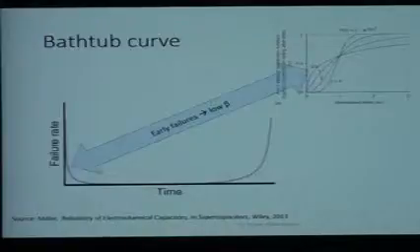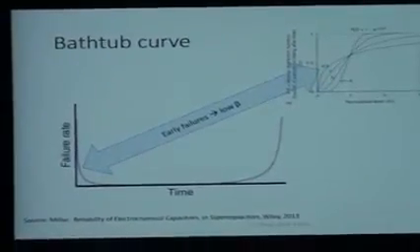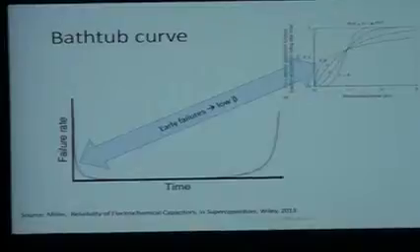Okay? So in order to handle this, I'm showing you in the inset here, if you have very low shape factors, beta, right? If you have very low beta, then that can handle the early failures. It has sort of an effect of capturing the early failures, and then you'd have to add another. So this would be like a convolved two-function Weibull distribution, where you'd have one beta for the early failures and another beta for the late-in-life failures.